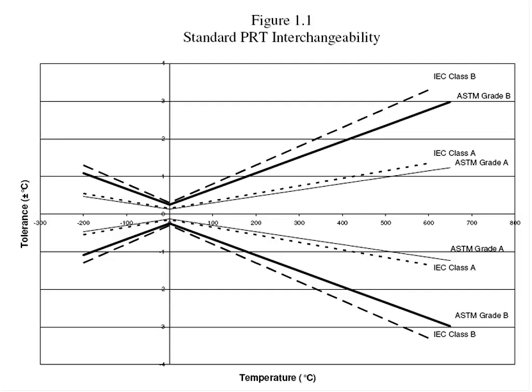One other interesting thing to see from this graph is that the ASTM standard has a slightly smaller tolerance than the IEC standard. That may be something to keep in mind when you're writing up a specification for an RTD.